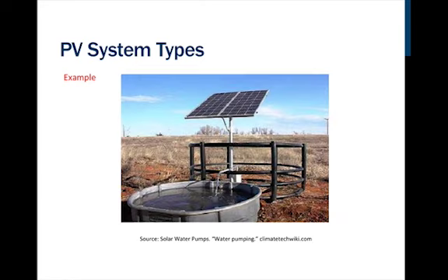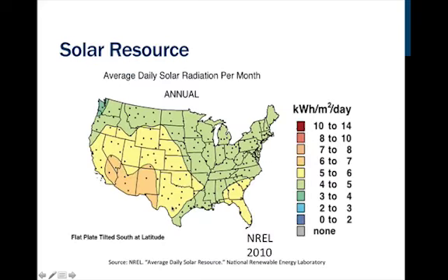Another type of PV direct system would be the remote deep well pump. Here we have a PV array sized for a deep well pump. And when we have the solar resource, we pump water into the stock tank. A float turns off the pump when we reach the top of the tank. And so we pump water when we have the resource. When we don't have the resource, we have this reservoir of water for the cattle. Works out very nicely.